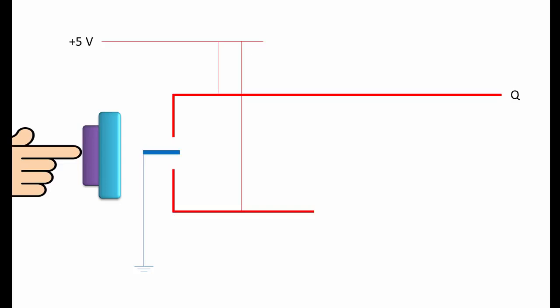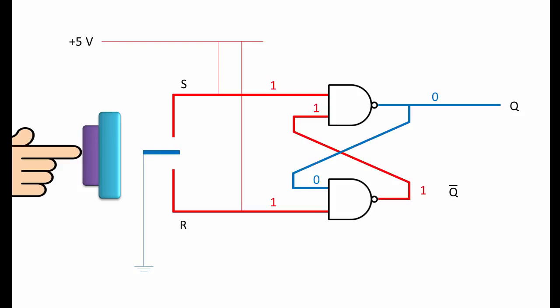Let's consider a particular application of an SR latch. When a mechanical switch is pressed, it may actually generate several electrical signals in a tiny fraction of a second, when only one signal is required. Lots of on-off signals like this could then cause problems with the circuit that this switch is supposed to be controlling. The effect is known as switch bounce. An integrated circuit with an SR latch on it can be purchased commercially to allow clean interfacing between a mechanical switch and the digital circuit it's controlling.